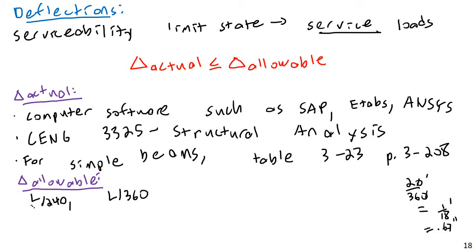In terms of when you use each of these, and there are other limits as well, these can often be found in various building codes. You can also find a version of the limits in the AISC Steel Manual. It's found in the commentary, actually, section L2 in the commentary. And that's found, again in the 15th edition of the manual, on page 16.1-478.